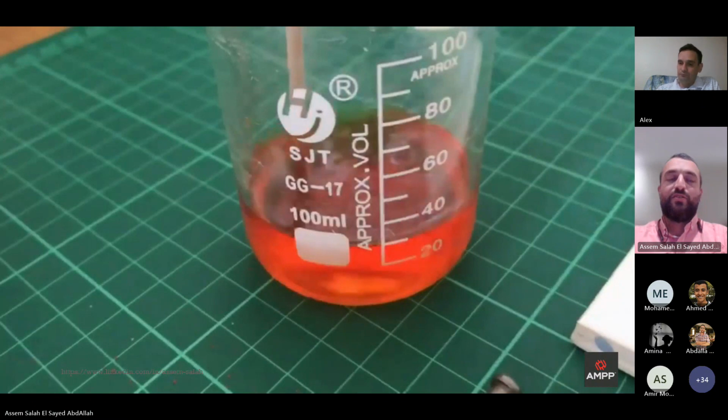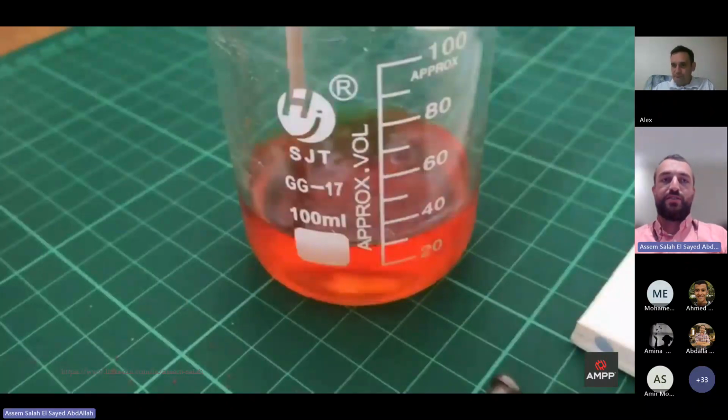Is coating, yeah. So to summarize what you have told us now, in the vessels we have two lines of defense. First line is the protection painting for the ship or the vessel body, and the other line of defense is the zinc plates, which is called cathodic protection, right? Yes, you are quite right. So, I mean, double protection, I would say, yes.